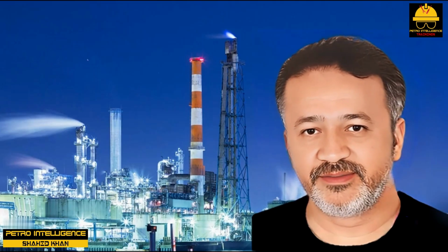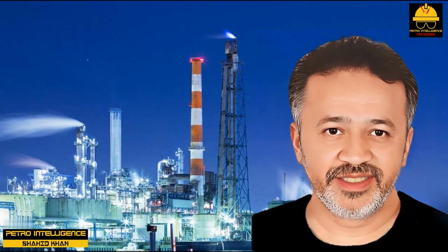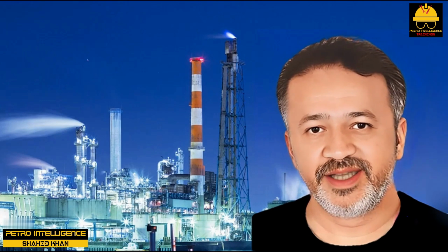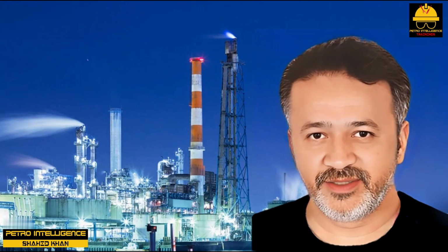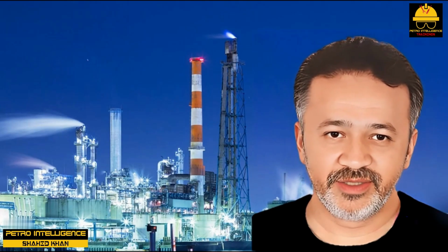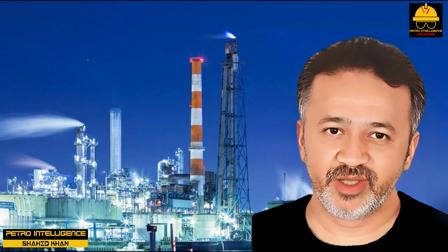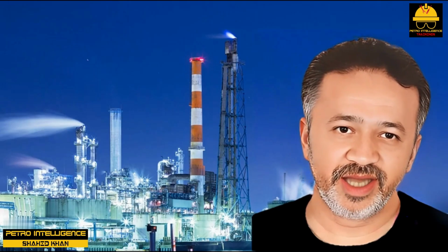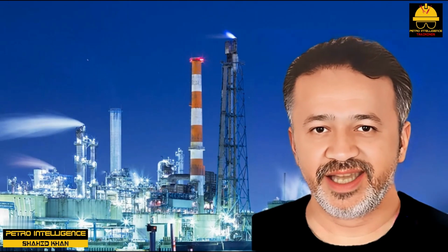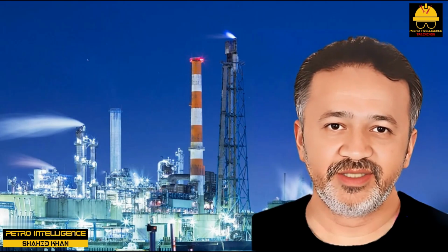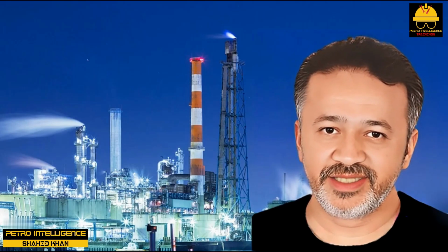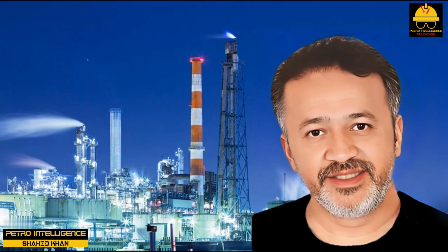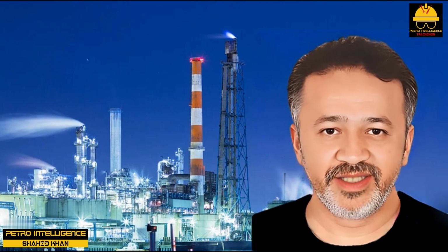Condenser operation. A closed-loop refrigerant condenser ought to be one of the cleanest services in a process plant. Even seal or lube oil leaks affect the evaporator efficiency rather than the condenser. I have measured rather high heat transfer coefficients, for example, 140 BTU per hour square feet degree F, in such condensers, even after that condenser has been in service for several years since its last cleaning. The most common problem with refrigeration condensers is condensate backup, rather than fouling.